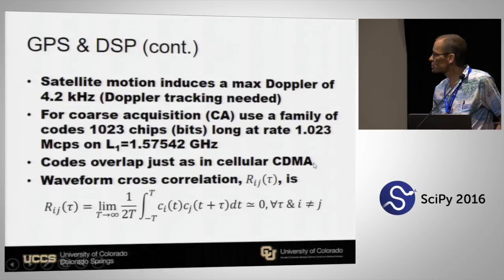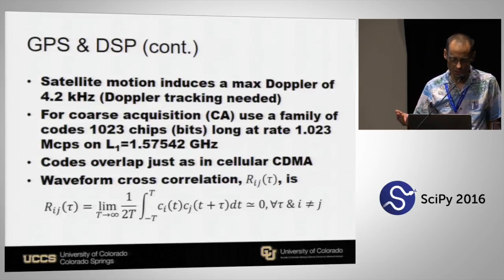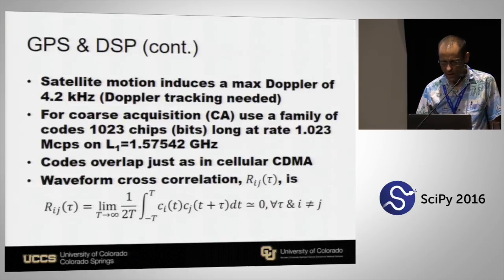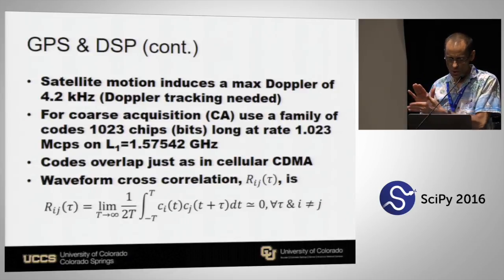How many of you remember CDMA? It came before what? What are you using right now? It starts with an L. LTE, right? Long-term evolution. But before LTE, we were in second generation cellular, so we have things like CDMA, code division multiple access. So how could everybody talk to the base station from their cell phone simultaneously? These signals overlaid on top of each other and were nominally uncorrelated with each other because the codes were orthogonal.